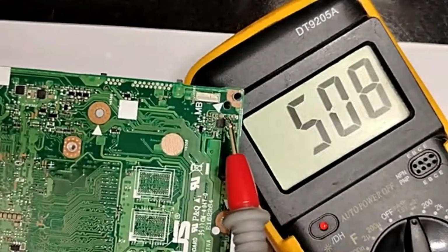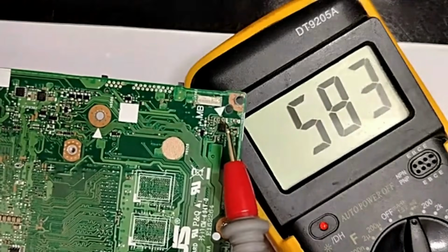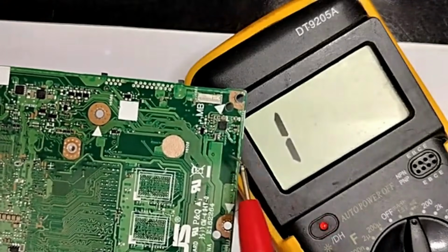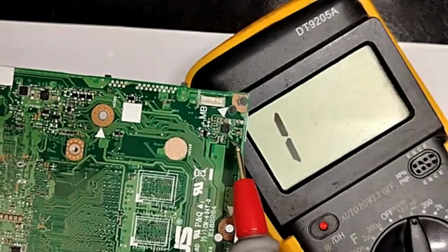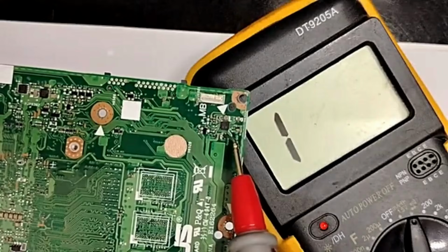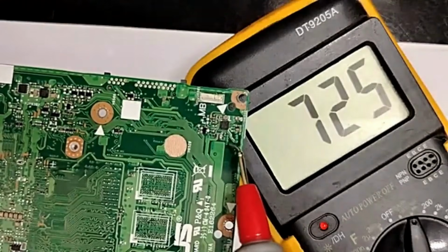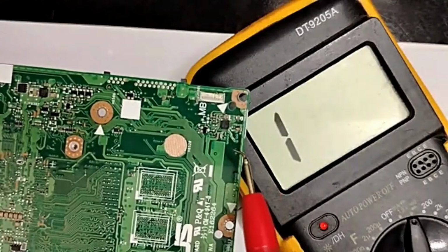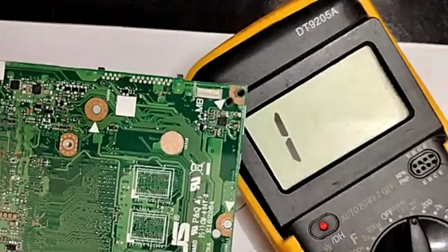This one also, it's not shorted on this side, but shorted on this side because it is connected to the ground. Because ceramic capacitors are always connected to the ground on one side and connected to the IC on the other side. Means it's not shorted. Means the IC is good, 100%.